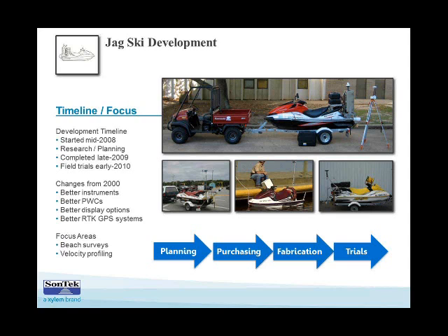And the Alabama Department of Transportation is actually increasing the width of this pass to promote improvements of water quality and increasing the length of their sheet pile jetties that extend perpendicular out to stabilize the inlet. And there's obviously some concern about trapping of sand, and so they required us to do the monitoring on a 3 times yearly or quarterly as-needed basis after a storm event to go out and keep track of sand volumes in the system and develop a sediment budget for this pass, and just to give them some guidance on how to improve their seasonal bypassing that they do mechanically with the dredge.